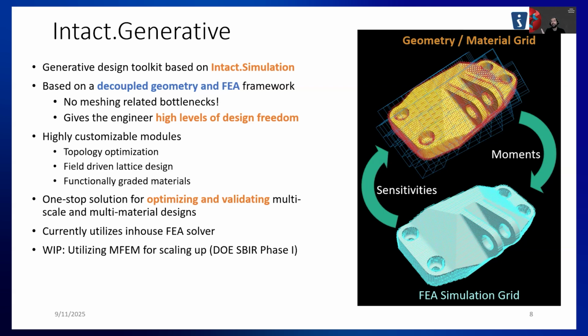16 gigs of RAM, 32 gigs of RAM. And our in-house solver, it's based on shared memory parallelization, OpenMP, and it can comfortably do 3 million, 4 million degrees of freedom. But we are running into situations where people need to solve tens of millions of degrees of freedom, if not hundreds. And what we have simply doesn't do it. So that's why we are talking.